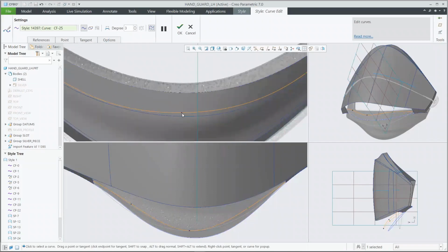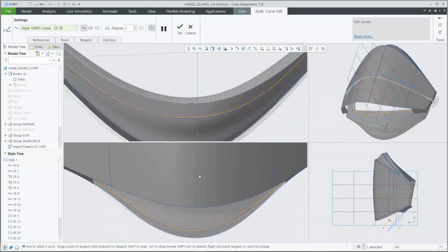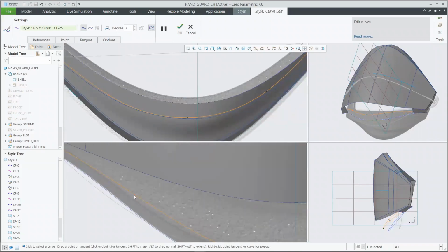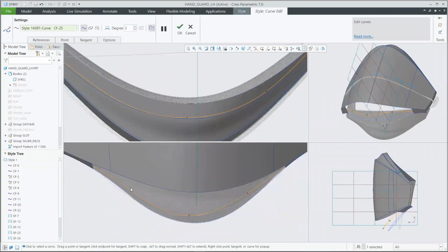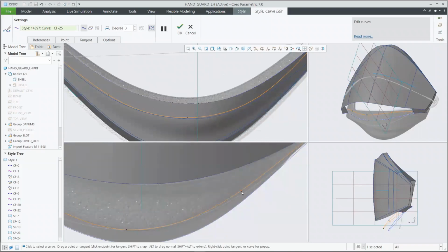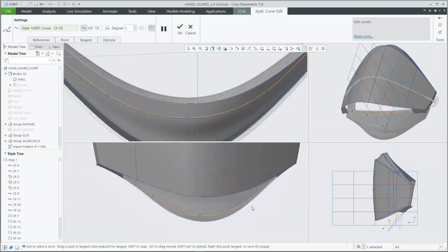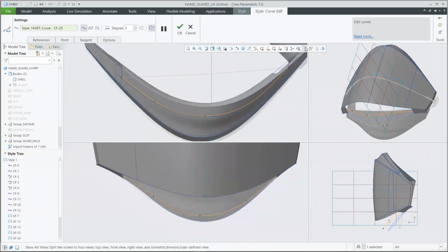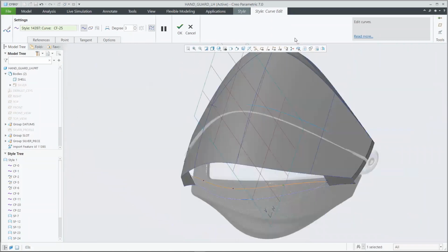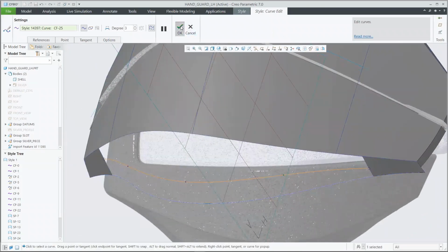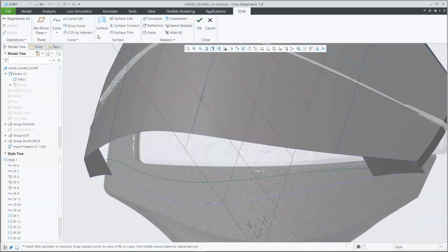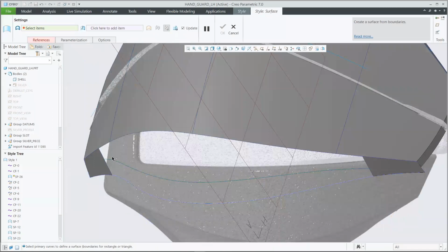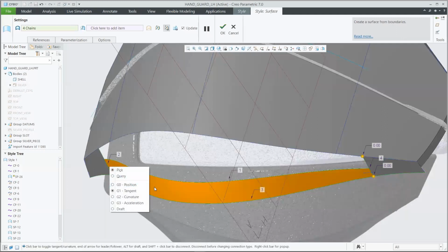And looking here, just making sure that our center curve is lining well with that initial curve or that initial sketch that we started with. And I think that's looking pretty good. So we can go ahead now and start to fill in that first area down at the bottom with the new surface. We'll do that pretty similar to how we did with the other two surfaces, just by selecting on the four curves that go along the outside here. Still making sure that tangency is in the correct direction.